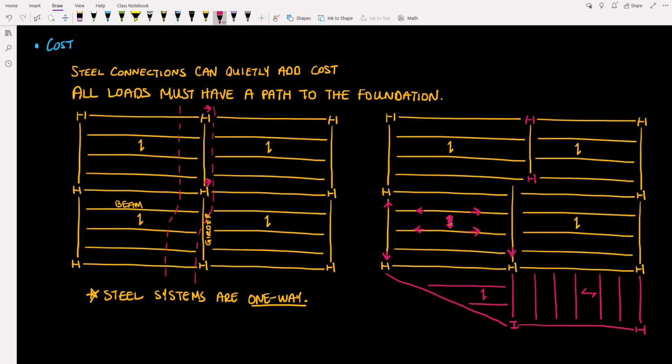However, the load that travels to the right, you can see that half will travel down the girder to this column directly, which is good, but the half that travels up the girder now transfers into another girder. And it's that extra step that creates complications, as now we need a larger connection between these two girders. Whereas before we could place a large connection simply into our columns, which are long vertical elements anyway. And so we have plenty of room to create a deeper, stronger connection.